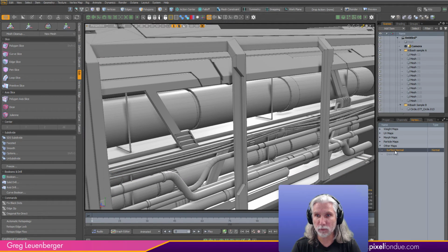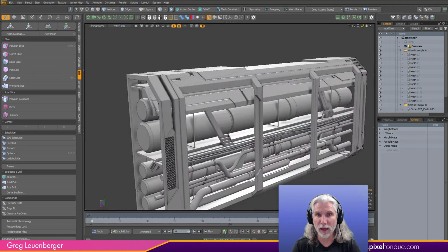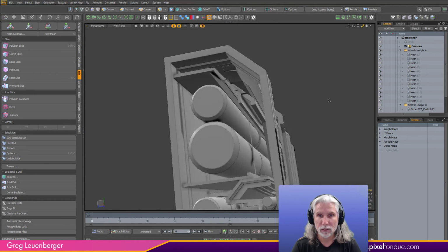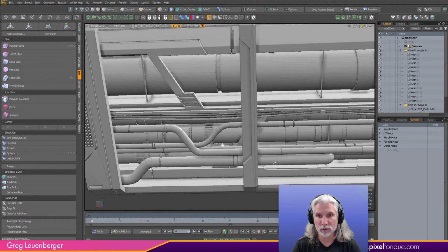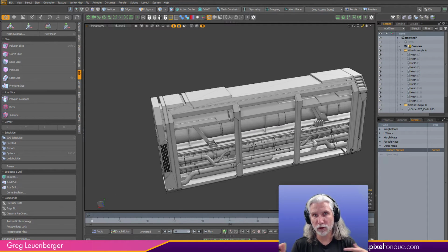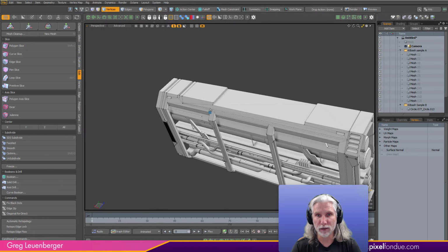And so if I take this, right click and delete it like that, sometimes everything looks fine, and sometimes you'll see shading errors. There's a couple of ways to deal with this. If you're not going to modify the geometry, it's best just to keep the surface normal there; I'm just undoing it. But sometimes if you're going to go in there and manipulate the geometry, Modo's modeling tools will often destroy those and kind of wreck your mesh.